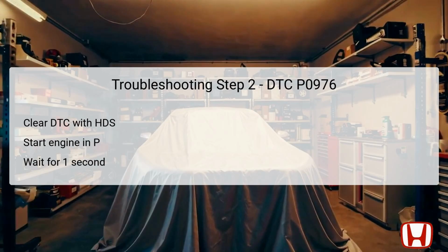In this step, you will clear the DTC using the Honda Diagnostic System. This action resets the vehicle's onboard diagnostic system, and clears the previously stored fault codes. Next, start the engine while it is in the park position, which is necessary to ensure the system operates under the least load conditions.